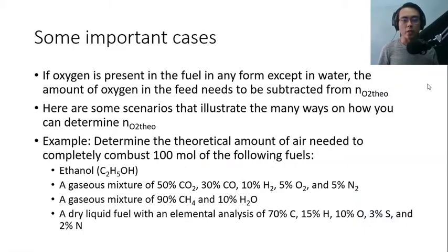We have here a list of some important cases that you always have to remember, because if you don't remember this, then your balances would automatically be wrong, no? Because we are very dependent on the value of the O2 Theo. If oxygen is present in the fuel in any form except in water, the amount of oxygen in the feed needs to be subtracted from O2 Theo. Okay? We are talking about the oxygen coming from the fuel.